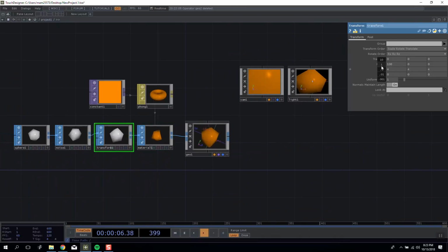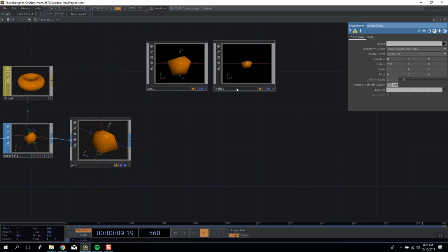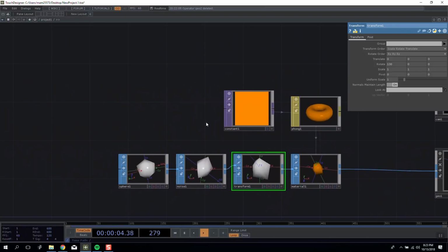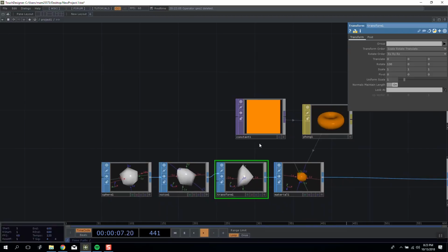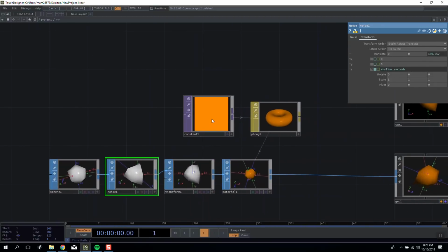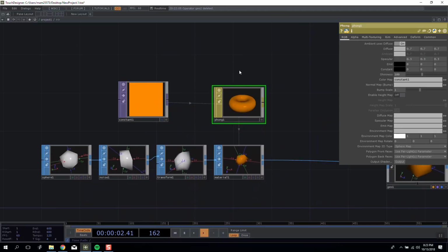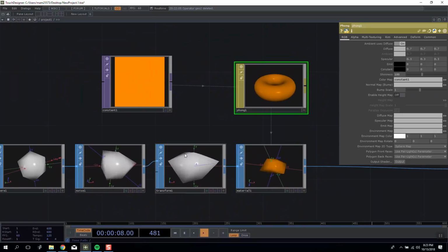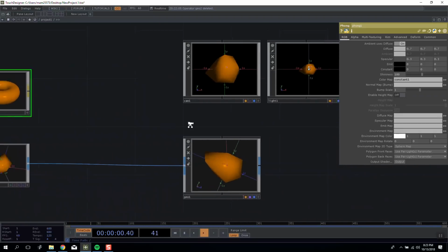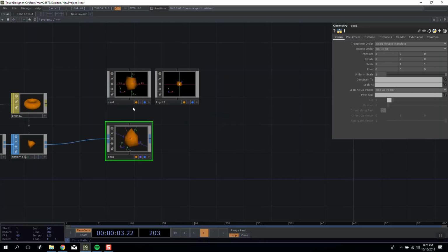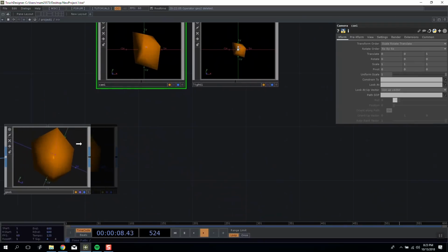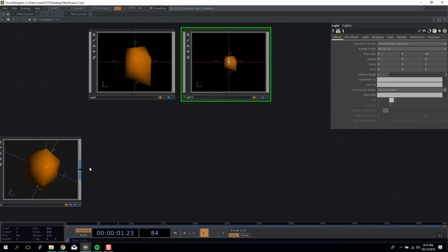I'm going to make my shape a bit smaller here so we can see it back to its original scale. So everything that's on the screen now means that we've made a 3D geometry that we are manipulating using time in our noise, and then we're applying a color to it with a Phong. So we're applying a texture that can accept light, but it exists only inside these nodes. Second, we do this and add it to the geometry container, add a camera and add a light, means that we've introduced this shape into a world space where we can manipulate it from a viewing perspective.